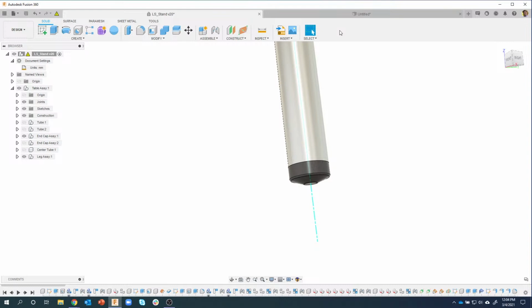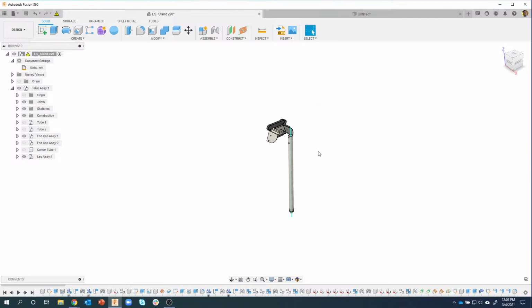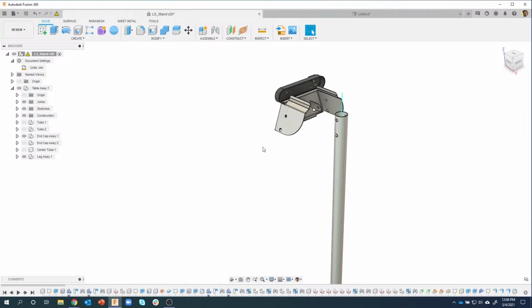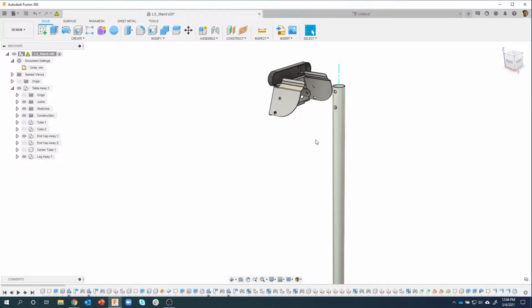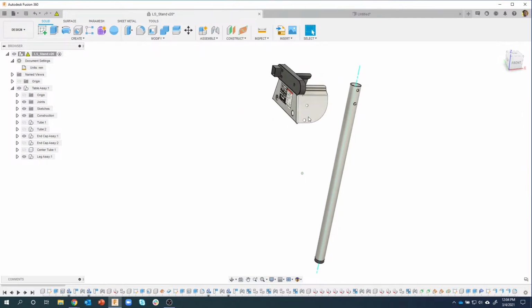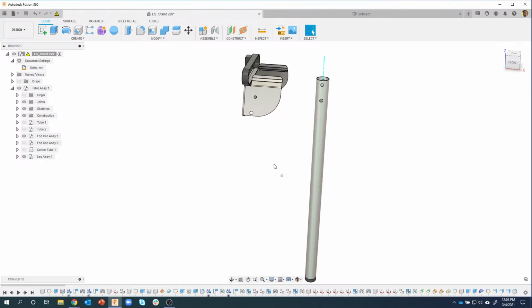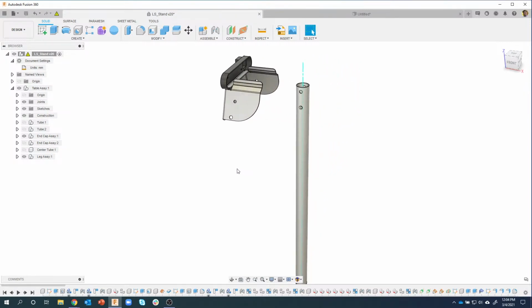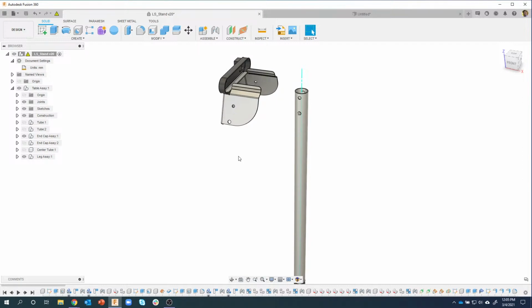Anyways, we designed the foot and we ran out of time to position it in the correct location. So that's what we're going to do today. We're going to create these legs and then we're going to work on the handle using some 3D sketch techniques to create this handle for moving the whole miter saw station.